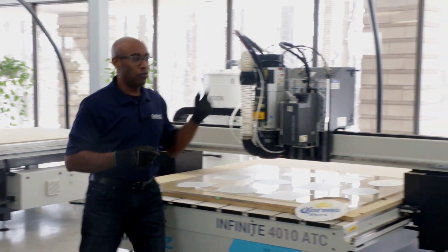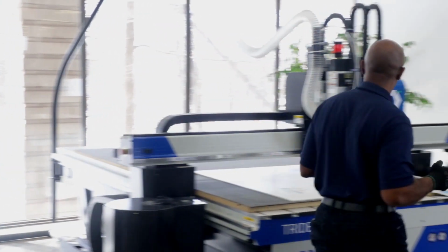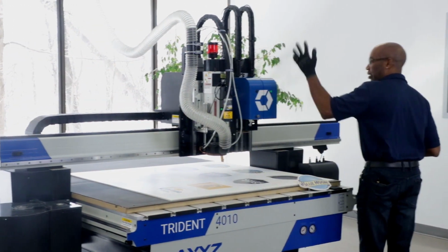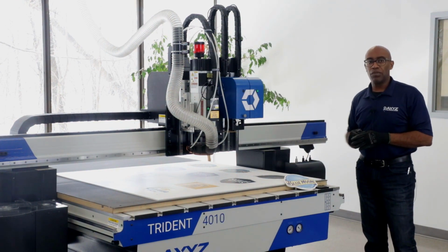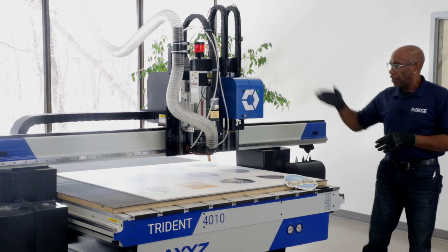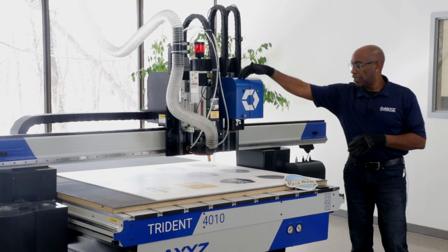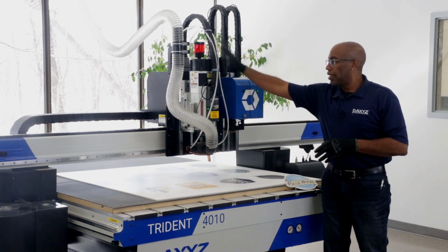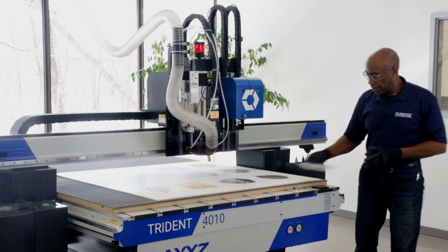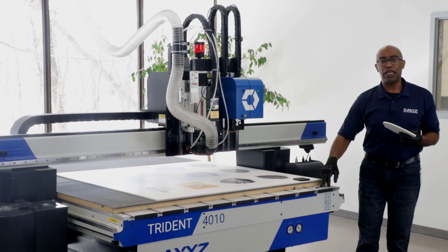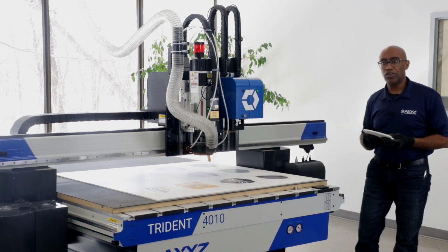Moving from the Infinite, we move over to our Trident. The Trident is purpose-built for the printer cut industry. We've added a couple of features to it. Our Z-stroke is quite a lot quicker for this particular model because we have rack and pinion drives. 2 knives, tang knife, 4-position tool changer, oscillating knife electric, AVS camera, 10 horsepower spindle, 10-position tool changer. Automatic light sensor for basically aligning your oscillating knife. All the different things you would need for this particular process or application.